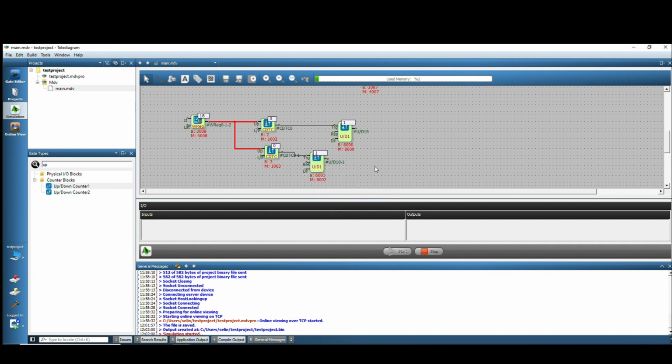For example, when we reduce the value 20 to 18, we observe no change in either. When it's 15, we again observe no change. But when it's 14, because there is a change of 5, it triggered. But since a 50% difference did not occur below, it did not send a trigger. For example, if we go below 10, that is, half of 20, yes. When we dropped to 9, a 50% change occurred, so it sent an instant trigger regardless of increase or decrease.